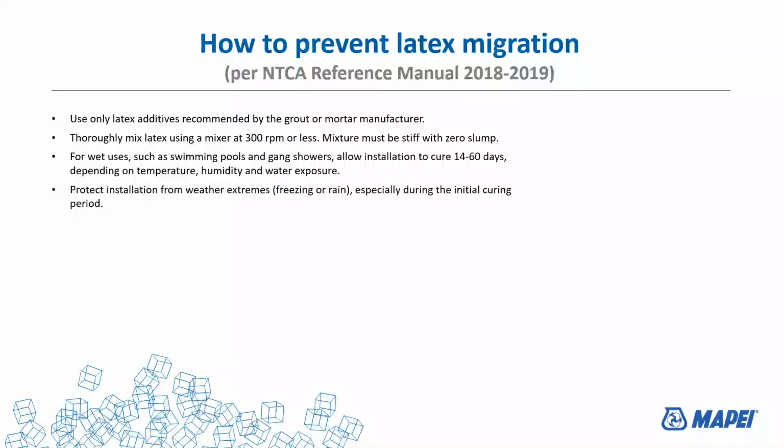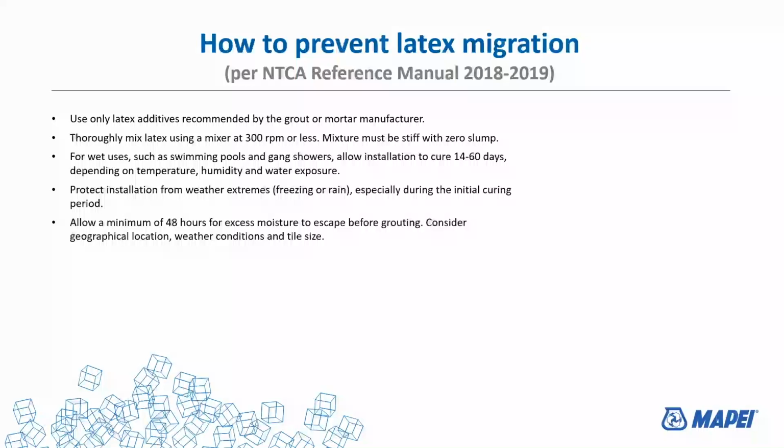Allow 48 hours is what they tell you on an installation to allow all the water to come out of the setting materials and out through the uninhibited grout joints before you start grouting. You've got to consider the conditions, imminent rain, the size of the tile, where you're at. It could be very high altitudes, meaning things may dry funny under certain conditions. So take all that into consideration.